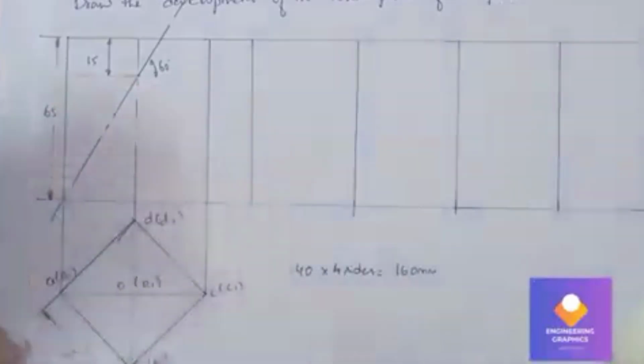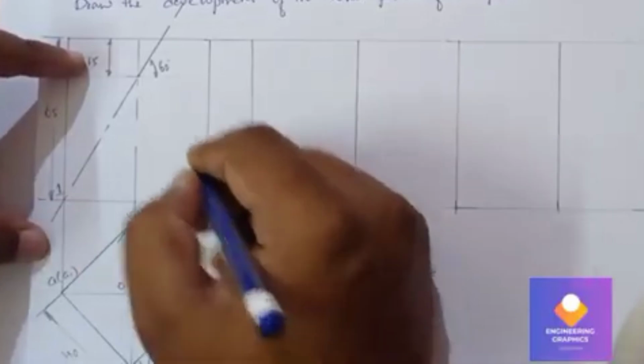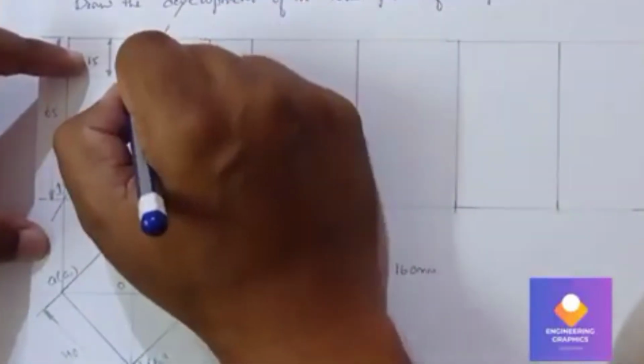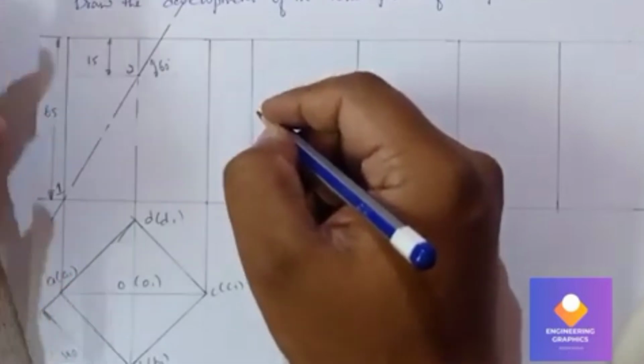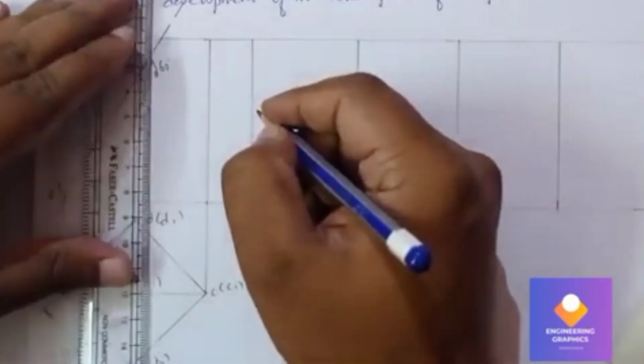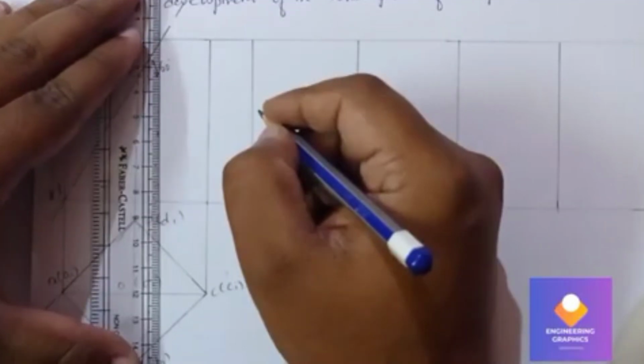Then after that you can see we have a cut plane here. It is exactly cutting at the A point here, 1, and here at the B point, and now at the C and D edge, this edge we don't have an exact point, so we'll be drawing vertically downward.